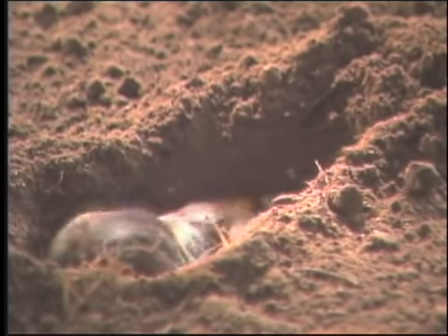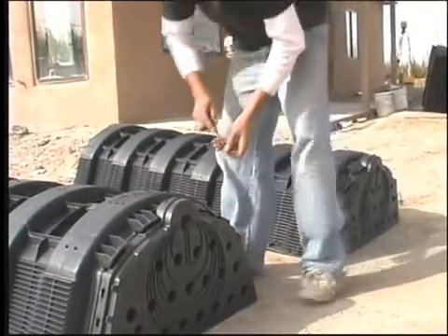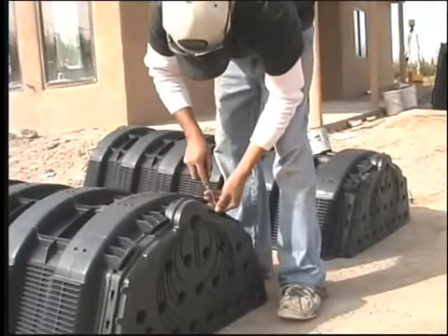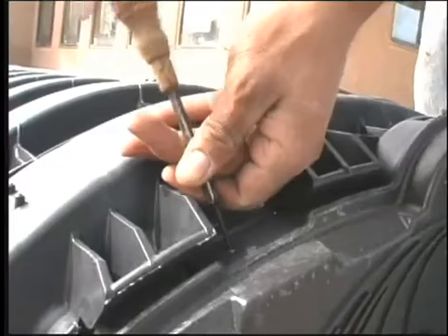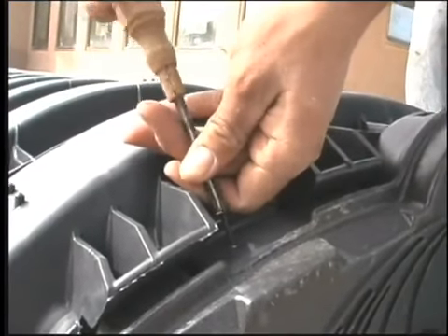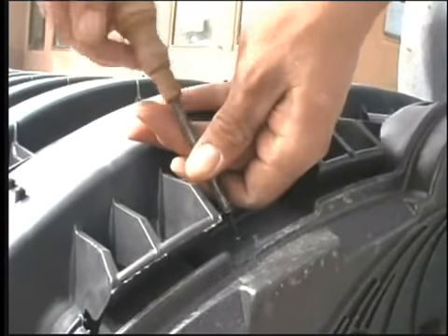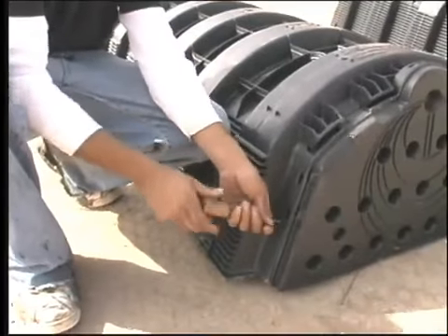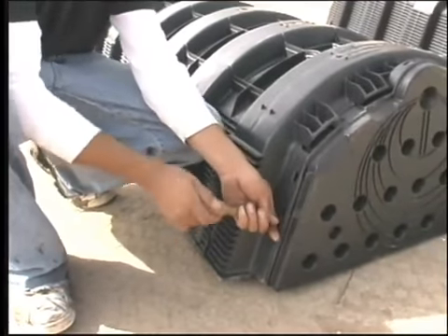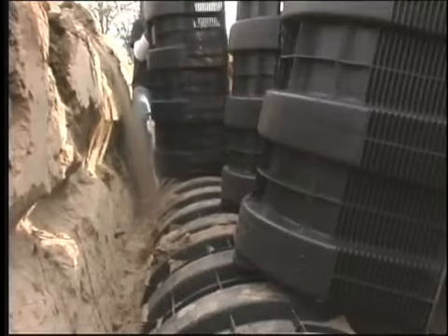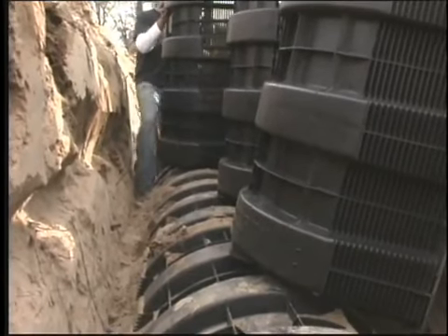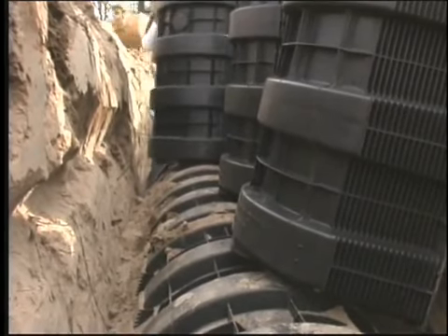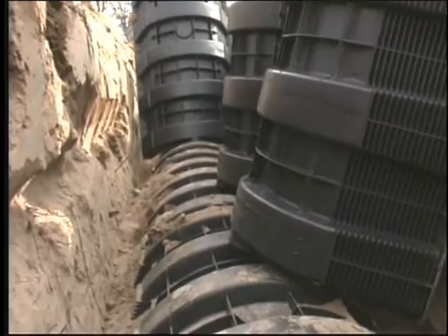Chamber system assembly is very simple. Screw the splash plate onto the bottom of the end plate for the first chamber. Screw the end plate into the inlet end, which is the end without interlocks on it. This is the end that will be closest to the septic tank. Do this at your convenience, outside of the trench or in the trench. Place this assembled unit in the trench with the interlocks facing downstream.